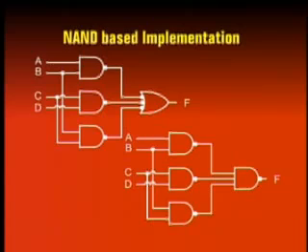The simplified 4-gate circuit can be implemented using only NAND gates without a change in the total number of gates. Bubbles representing NOT gates are placed at the output of the 3 AND gates, converting the 3 AND gates to NAND gates. To balance out the 3 NOT gates added at the outputs of the 3 AND gates, 3 bubbles representing 3 NOT gates are also placed at the 3 inputs of the OR gate. The resulting OR gate symbol with 3 bubbles at the 3 inputs is an alternate symbol for a 3-input NAND gate. The NAND gate based circuit is shown.